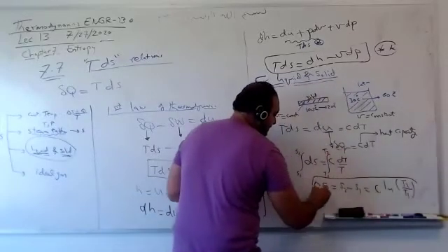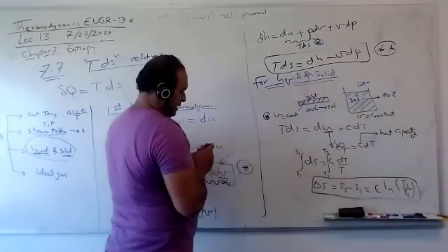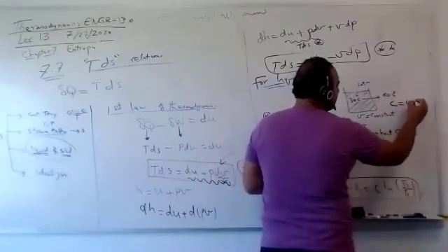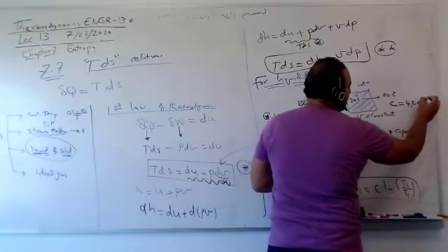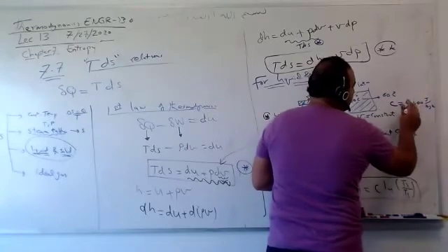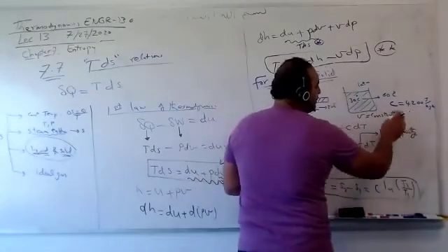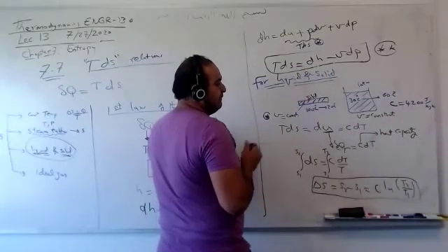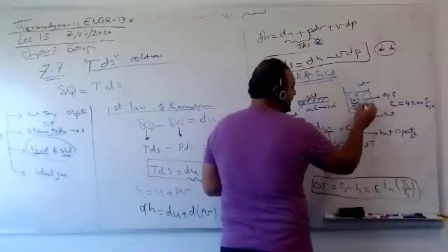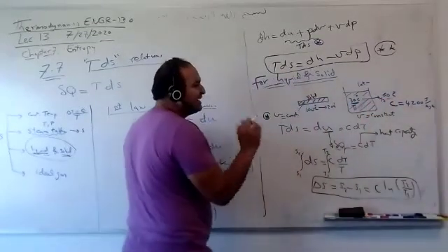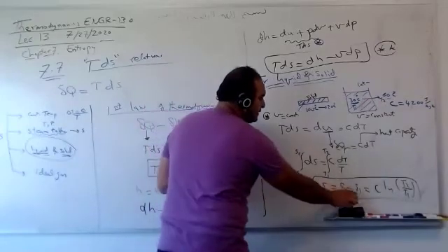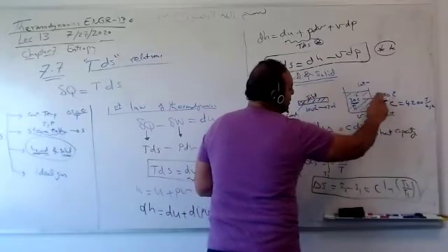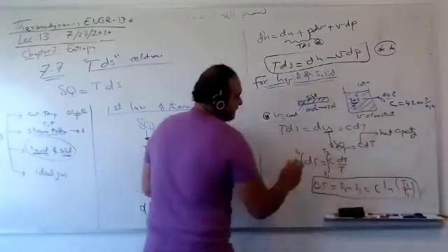So if you have water, if you have solid, let's say water heat capacity was about 4,200 joule per kilogram Kelvin. So you need this heat to increase 1 kilogram by 1 Celsius for water. It's a constant. If you heat from 30 to 60, this is T1 and T2. If you want to know how much entropy change, S2 minus S1, it's just C ln T2 over T1. This temperature in Kelvin over this temperature in Kelvin, you can get delta S.